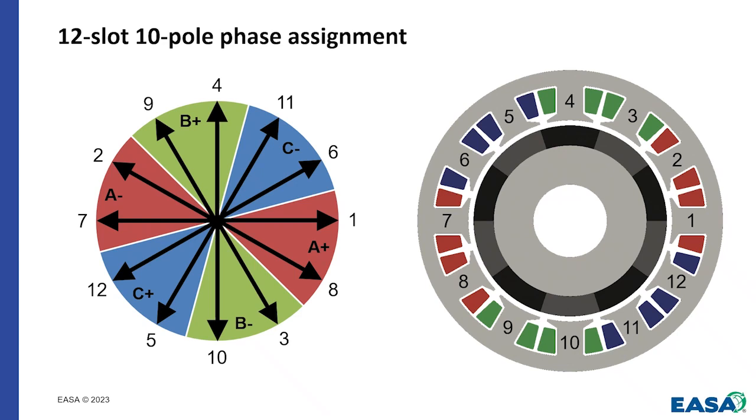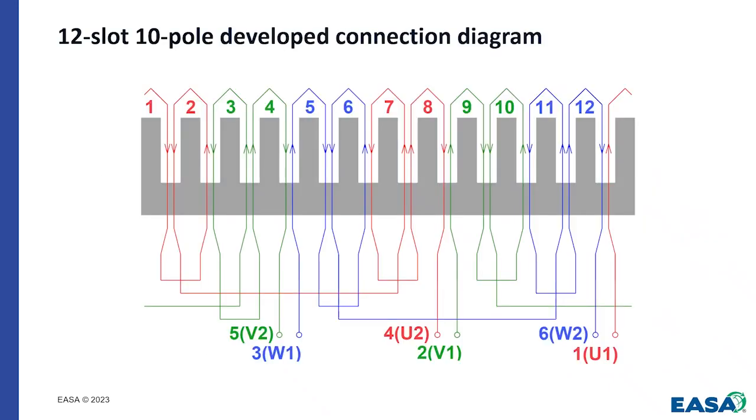So from that, we can develop your standard typical connection diagram. That again, if we didn't go through this, showing how these can work together and should be connected together, it's going to look a little bit screwy. Because we've got our A phase, or line 1, going in this first slot coming over. And then right beside it, we've got another coil that's in the same phase, but if you look, the polarity is opposite. That's unusual. Normally we wouldn't have that, but it's because of the 5th harmonic is what we're looking at, that 150 degrees electrical between the 2, that's going to make this all work.